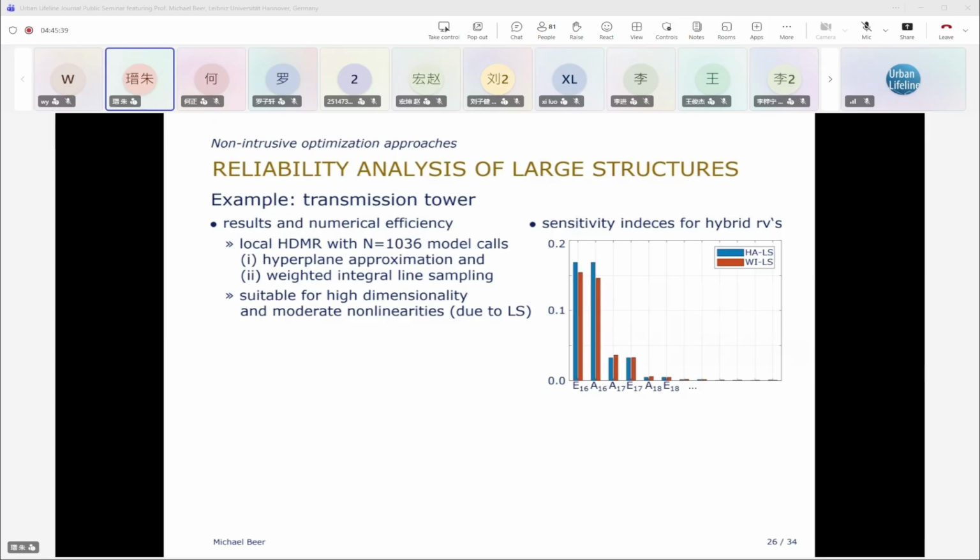So based on that result, estimating just the first order terms, this is a sensitivity analysis for model order reduction. Here we would say, okay, 4 parameters is enough, the rest has almost no influence. That means we don't need to do this for all the parameters, we only find the critical ones. And that reduces the numerical effort and the complexity even further. So that is a drastic reduction of numerical effort in the end.